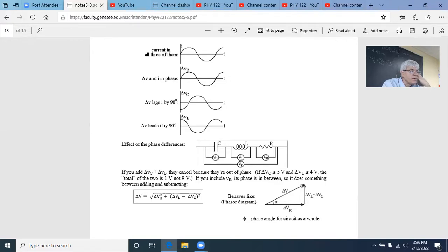that the total voltage across all three of them, what would be read, I drew this all in the diagram there, the little circles with V's in them, those are supposed to be voltmeters, okay? So the diagram supposedly shows a meter reading the voltage across the capacitor. I called that voltage VC, and another meter reading the voltage across the inductor, and I called that one VL, and a meter on the resistor. And then VT, that's a meter that reads the voltage across the entire group.